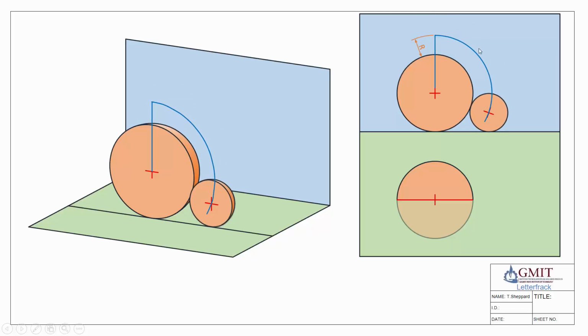If we draw a sphere of radius 20 millimeters anywhere with its center on this arc here, it's going to be in contact tangentially with our original sphere. So we've done it there for rolling around the sphere. We're going to do the same as we did last time, rolling it along the horizontal plane, and where the two cross gives us our common point. That's our common point in elevation. Like we did last time, we bring it down to our plan view, straight across from our center, giving us our location in our plan view.